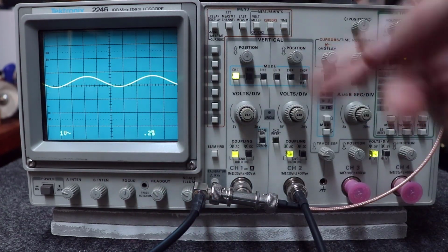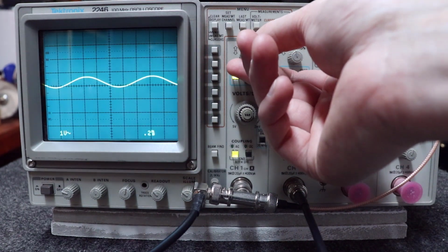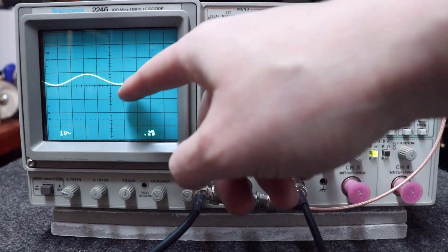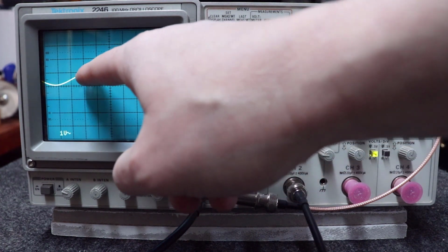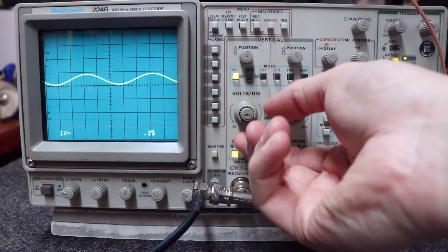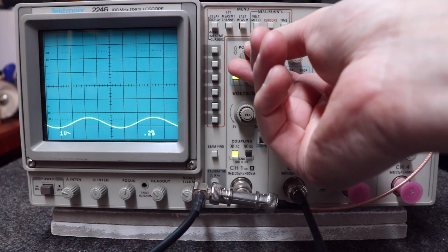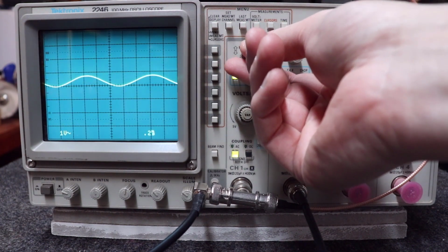Remember earlier I said this was a 0.8 volt peak to peak signal. So if I move this up till it's sitting on the middle line, it would take me up to just below the next little line there, and I would be seeing that I have a 0.8 volt signal there, okay? Now you notice something I showed you. I showed you the position. This is arbitrary. You can put it wherever you want, right?